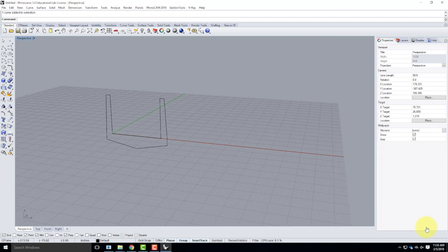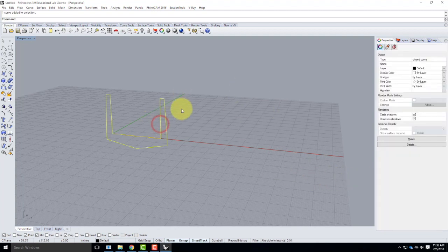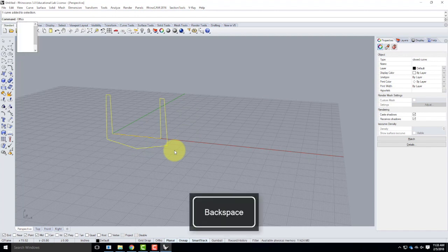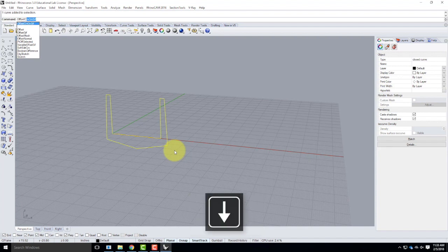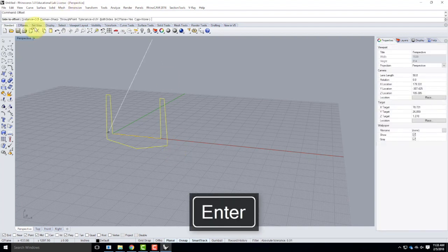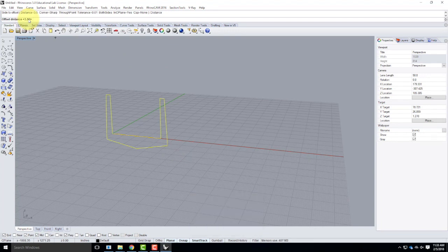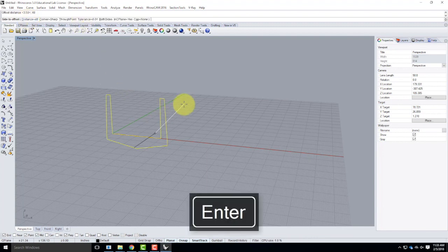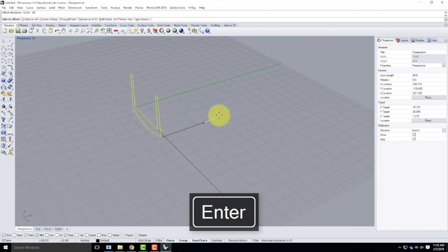OK, so now the next piece of this is I need to offset this curve, so I have a second set of this curves behind over here. So I'm going to type in offset, just plain offset. And my distance, I need it to be, what did I say, 48, didn't I? There it is, 4 feet, so 48, or 4 feet. I'll hit enter there. And you see by default, I am going back in this direction.